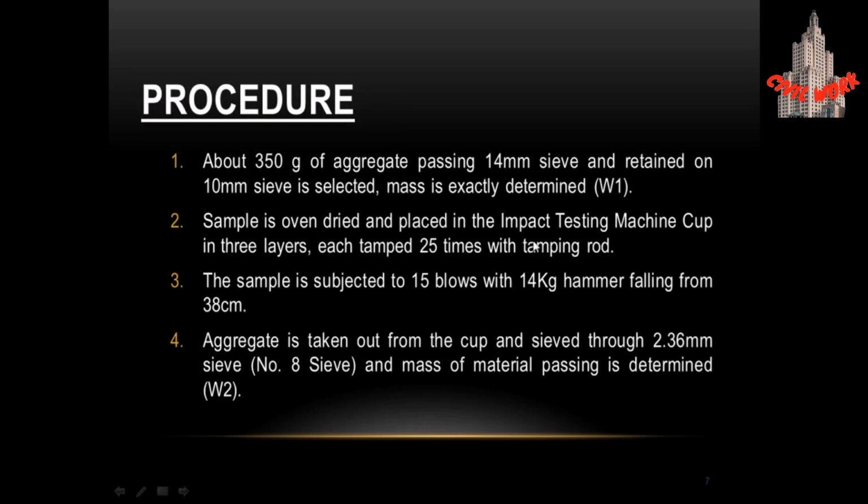Point number 1, about 350 gram of the aggregate passing 14 mm sieve and retained on 10 mm sieve is selected. Mass is exactly determined as W1.